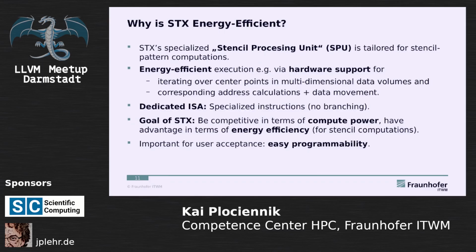In combination with this hardware support, we also have a dedicated instruction set architecture, which has specialized instructions to program for this architecture. Something I will mention later in the talk, so you can remember it: the ISA, the instruction set architecture, has no branching instructions. And that causes some challenges if you want to write a backend for this in LLVM.